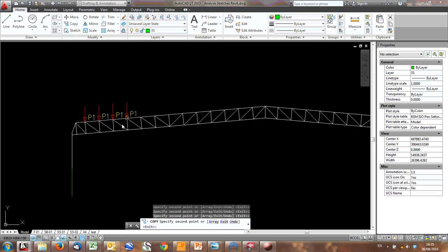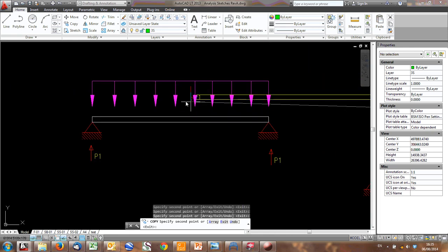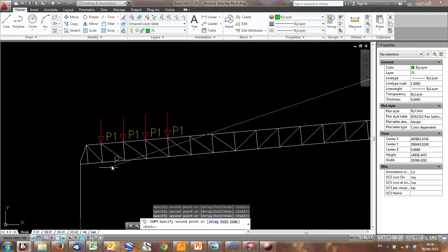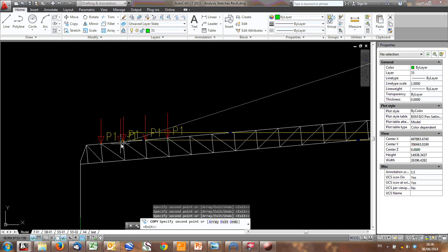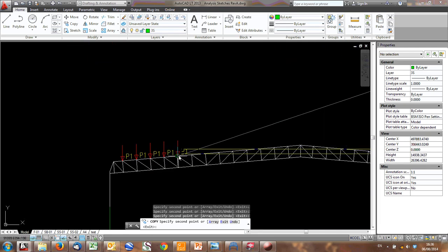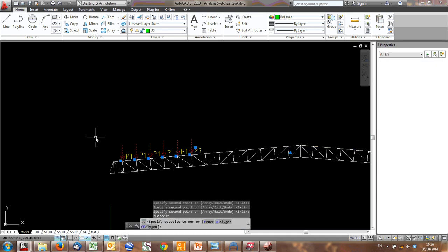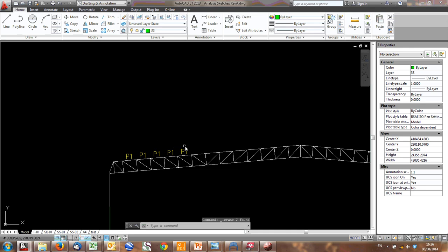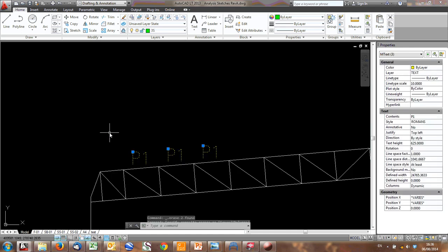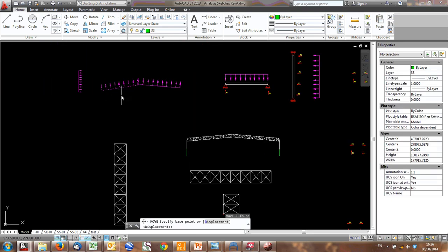And that is the way you can start sizing it, because what you do here, you size this for your live load, or you analyze it with a live load, and you get a reaction and a dead load, etc., etc. And suddenly you have a load that you can apply there. You can apply those all the way along. With this many point loads, though, what you'll find is it almost approximates out to a uniformly distributed load. So, depending, you have to be careful doing it, because it's an approximation of all these point loads, but you could otherwise provide a UDL all the way along.